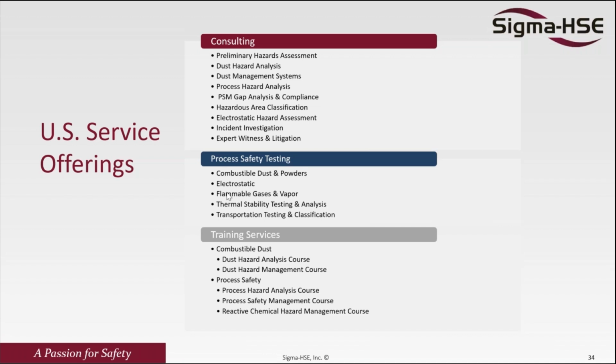Clarify the type of safety shoe that should be worn, assuming the floor is conductive. Normally, you have ESD shoes, which are super common in the market. If you are looking for any, you go to Amazon, you type ESD shoes, and normally you need to test them. In case you use ESD shoes, you need to have something to test them. But this is super common in the industry, and you can actually use it from the market.